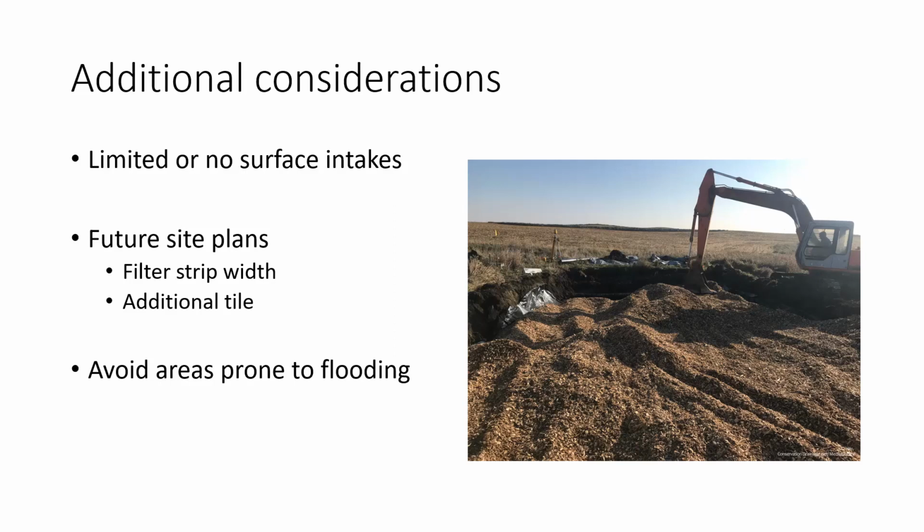If that tile system really only drains that terrace and serves that purpose, to get the surface water behind the terrace out of there, you generally don't have a lot of nitrogen in those types of situations. So it's not really worth the added step of doing the wood chip denitrifying bioreactor, because that water that moves to the subsurface, that's where we're picking up the nitrate in that tile load.